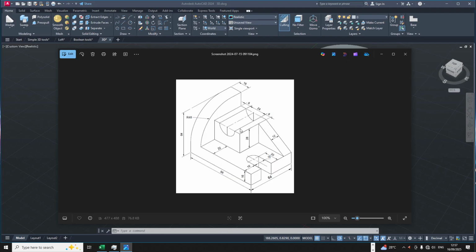But most times, when we want to see that you understand, especially looking at this guy, you will see that you have to use 2D objects to cut holes into 3D objects and stuff like that. So the idea is to see whether you really understand using the dynamic UCS, the view plane UCS, or the WCS to draw these things.